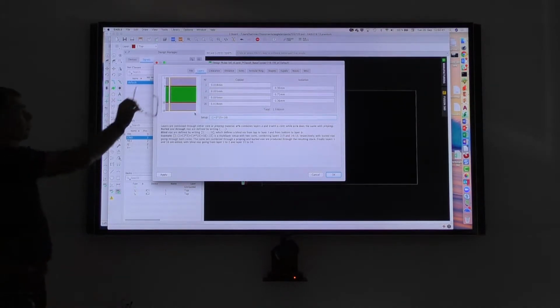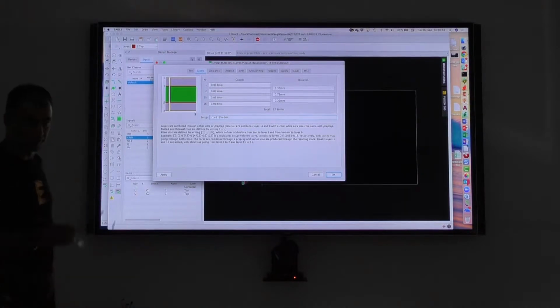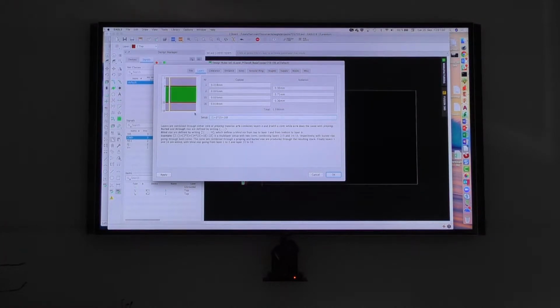The best is if I do a drilling through the whole stack. So that's a via, and we have so-called blind vias. Blind via means you can't look through it. It goes from here to anywhere inside. And this in the production process is much more expensive because you have many more failures in the production, and you have to pay for it. The board manufacturer does not pay it for you. You have to pay it, and that's the reason why such more exotic setups are much more expensive than the standard ones.